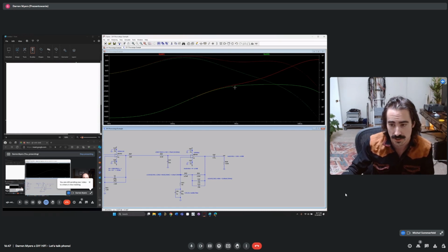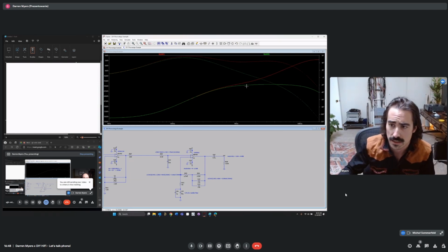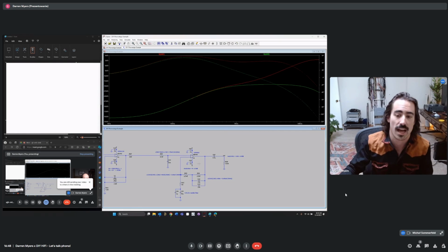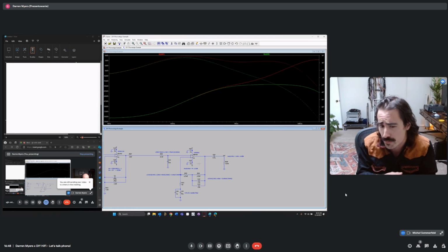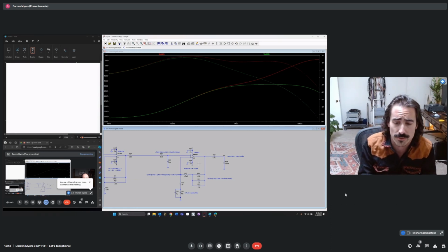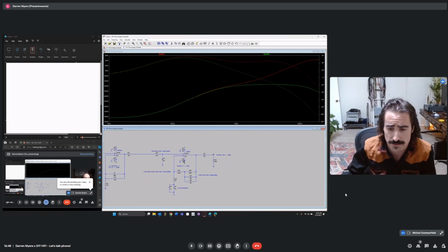I think we can all agree that our ears are very sensitive, probably in this region here from 500 hertz to 3 kilohertz, an ultra sensitive region for the human ear. And so it's nice not having to have a huge swing in the amount of feedback applied in the amplifier here. So that's another advantage, a little bit more of an advanced concept, but one of the reasons why people have tended to start to go towards these hybrid setups more often.